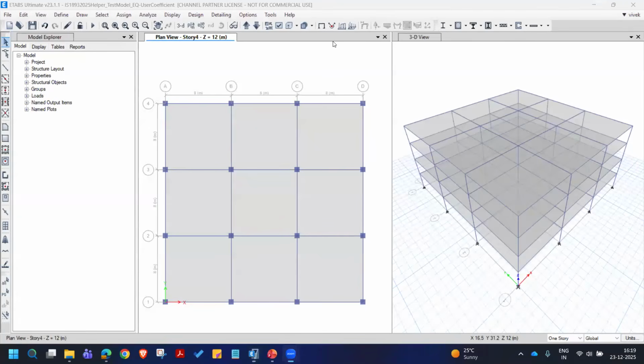Yes, for the vertical acceleration, that equation R has been omitted. So it has to be full value without any reduction, elastic reduction factor. That is the current. So the comparison I already showed you just for the horizontal one, that itself can reveal it as double the value of earlier code.